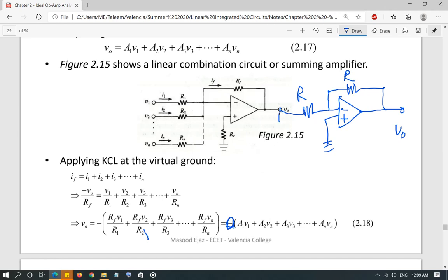So let's say this is V out 1 and this is the total output, then V out will be equal to V out 1, since the gain is 1, RF over R input is 1, but the output will be opposite of the input. So since this is negative already, as you saw, this is a negative sign, then negative of negative is going to become positive at the output. So this is one way that you make the output positive instead of having the negative output.